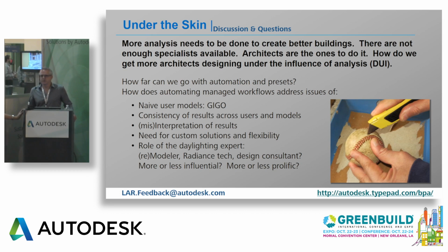Right, great question. So tubular skylighting devices are pretty much not really possible to model except with a reverse ray tracing algorithm that's very, very complex. So the way they do it in both Radiance and the way we do it also is to get an IES lighting file, which is a lighting distribution for a particular time of day in a particular place that we put into the model and then treat it like an electric light and just turn that on.